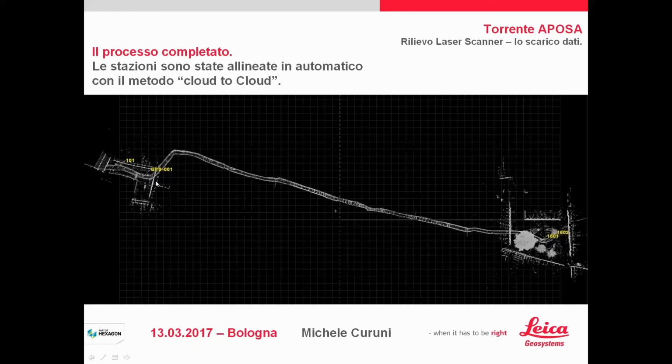These two dots were picked by the surveyors of Bologna. They hosted us and invited us to do this experience. They fixed a point outside, of course, with GPS, and one point with the total station. Then we followed the topographic method called traverse, which is a method to move the total station with high precision along a path.